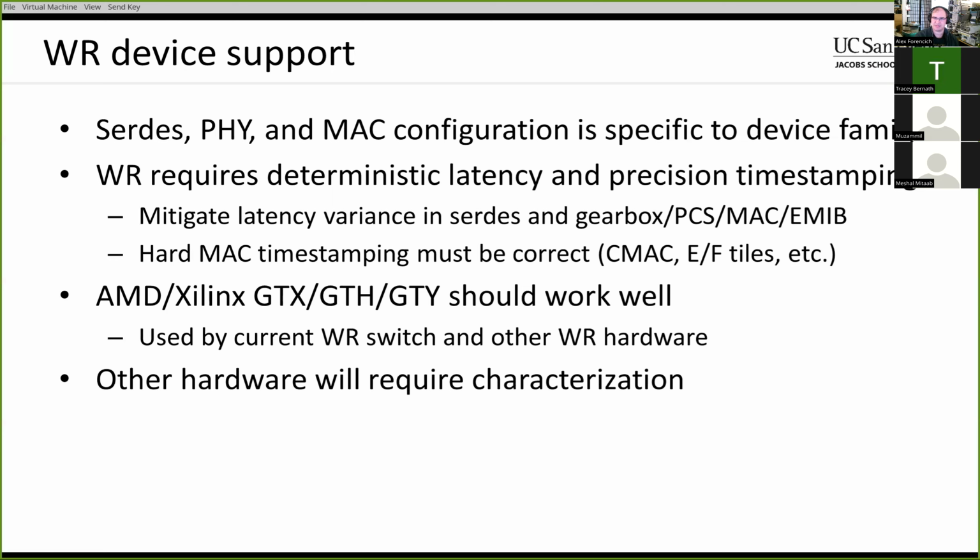For the AMD Xilinx devices, GTX, GTH, and GTY, I think they're all very similar, and the current White Rabbit switches use these transceivers, so they should, with the quotes around "should," work more or less out of the box without too much screwing around. They should be relatively well understood at this point. Other hardware, I think, is going to require characterization, so we'll cross that bridge when we get there, basically.